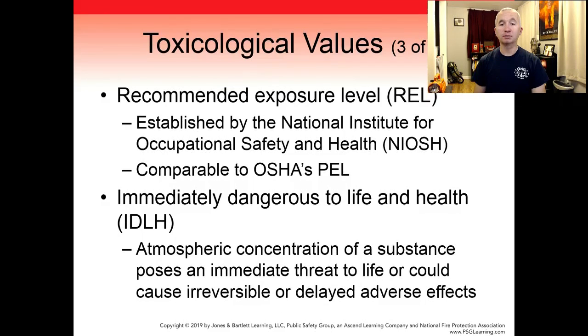The recommended exposure limit is the value established by the National Institute for Occupational Safety and Health. It is comparable to OSHA's PEL. The designation immediately dangerous to life and health, IDLH, means that the atmospheric concentration of a toxic, corrosive, or asphyxiant substance poses an immediate threat to life or could cause irreversible and delayed adverse health effects.